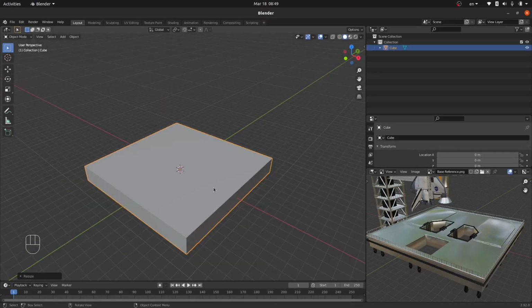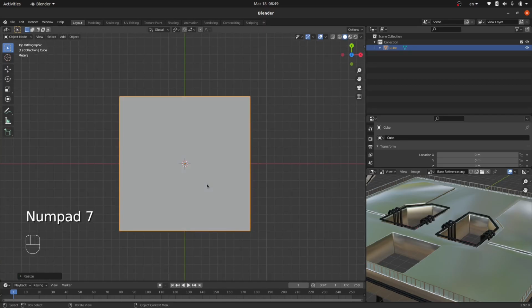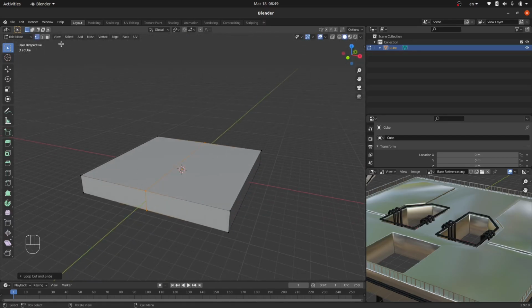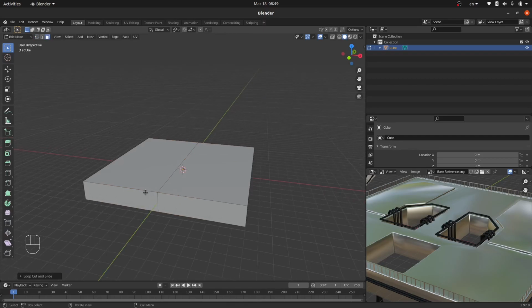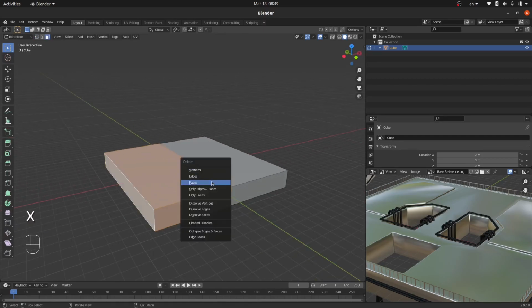And after that, what I'd like to do is I'm going to be making some cuts inside our base. You can see that over here from the top. So I prefer this way. I prefer to cut it by half and add the Mirror Modifier. So this one is going to be replicating those steps again. So Control R to insert that edge loop. And also over here I'm going to hit Alt to select the entire row. And also this one, and X delete.